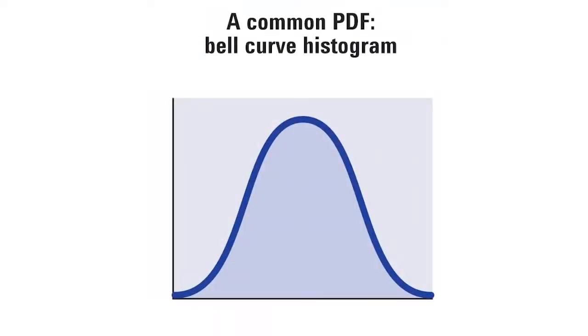Fortunately, there is a better way to look at the data using probability distribution functions, or PDFs, to display current drain values logged over a given time period. A PDF shows current drain values on the horizontal axis versus probability of occurrence on the vertical axis. Histograms are a well-known version of a PDF. But histograms are not very useful for analyzing battery current in mobile devices because of the extremely wide range of current values demanded by these devices.